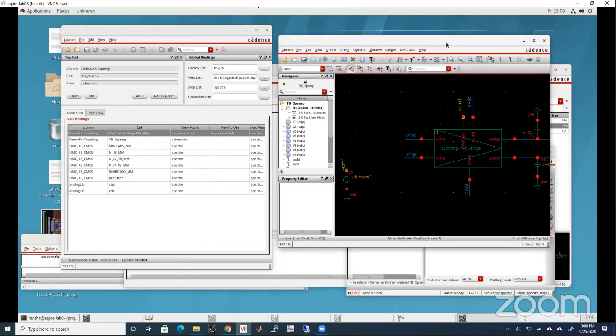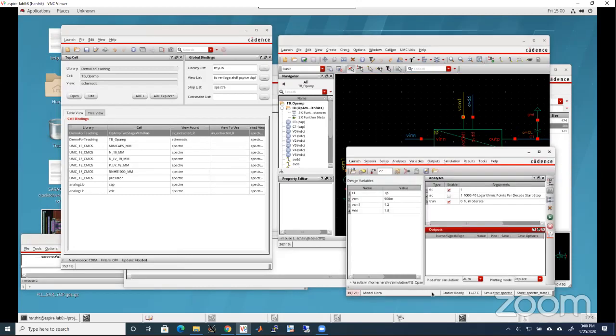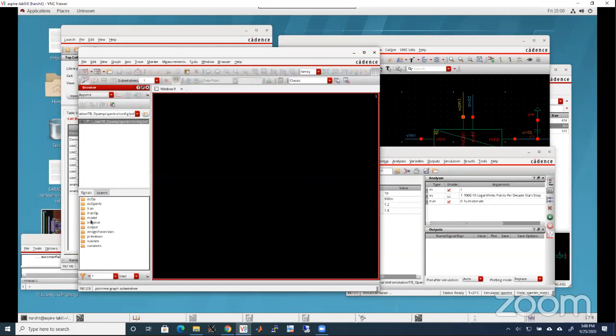I ran the simulation. Now you will see how many power nets, the resistance of the power line VDD and the ground line have been broken into multiple nets because it is the R only extracted simulation. So I will see how bad is the power delivery, means how close is it to ideal. Okay. So I'll go to the tools, results browser. That's the only way you can see, and transient.